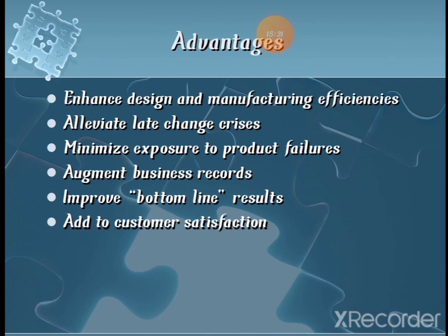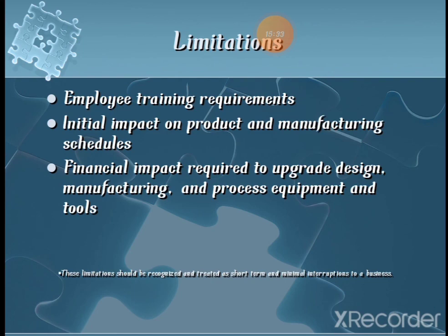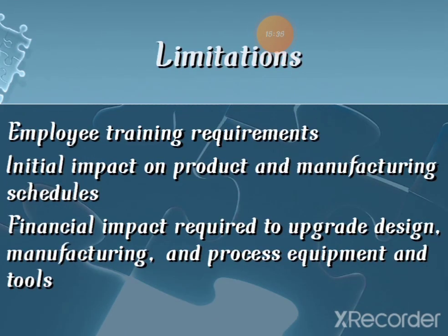Okay, now we will see disadvantages. What are the disadvantages of FMEA? As we all know, FMEA processes may be tedious, that is, time consuming, and also expensive. The approach is not suitable for multiple failures. When there are multiple failures, it cannot be approached. It is too easy to forget human errors in analysis, as human errors are not calculated here.